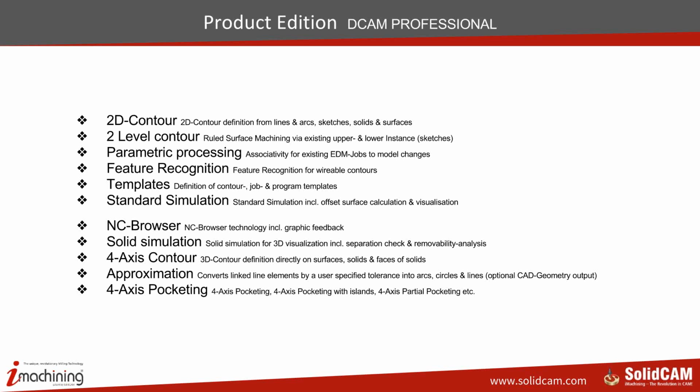Also, there is a slug checker, which checks your slug removability, and the software will automatically tell you is your slug extractable or not, which is a very nice feature. And if it's not extractable, you need to create additional operations in order to extract those slugs.